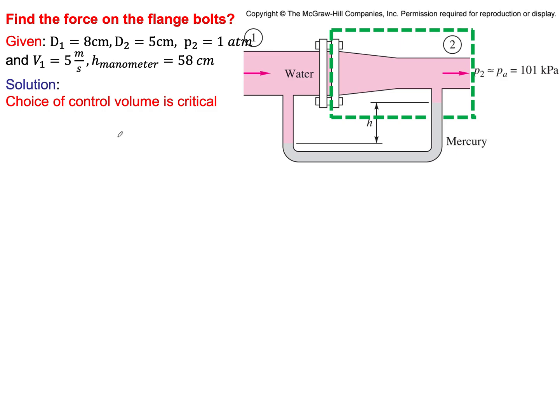Okay, so you're always better off starting. So we're after the force, but the smarter way to do it is to always start with mass conservation. Mass conservation is an algebraic equation. It's easy to write and implement. So you're at a control volume, you might as well just start with conserving mass, because that mass is really what's carrying the momentum. And if you don't know what mass flow rate is going through your system and its distribution through the conservation equation, then most likely your force balance is also going to be off.